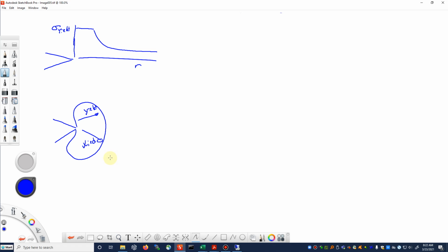Now, even this isn't completely right, because the equations that we've based this on are linear elastic fracture mechanics equations, and we've just set the value of that zone equal to whatever the yield stress is. So it's not completely right, but that gives you a pretty good estimate of the 2-dimensional shape. Now, what we're looking at in this first picture, if we were to think of this size right here, would basically be this part of it right here. Okay, so this red circle and this red circle correspond to about the same thing. And so an easy way to characterize the yielding ahead of the crack tip would be like the diameter or the radius of this zone right here.